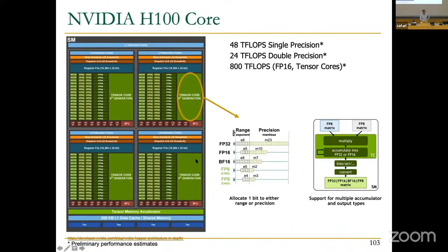Okay, so you can see that people are adding more data types. Why? They figured out that operating on 16-bit data, 32-bit data, floating point is expensive. We can actually do machine learning inference and sometimes training on smaller data types because we don't waste a lot of computation. So they've added these floating point 8 units, for example. They actually play a lot of tricks. You can see that people are trying to make this accelerator much more efficient.